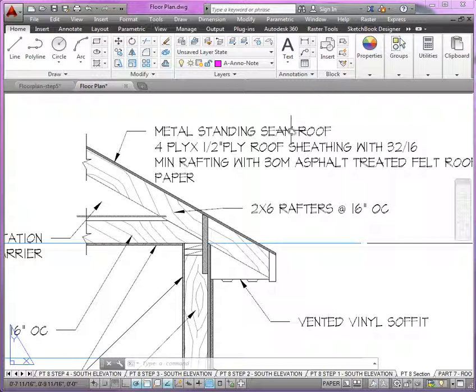It's not actually showing you the finish. What could we have as finish? We could have asphalt tiles as finish. We could have Spanish tile as finish. We could have aluminum or metal roof as finish. So the finish thickness here is going to be different. All right? And it's only going to be 1 or 2 inches. We're still going to be accurate enough for architectural review or plan check.